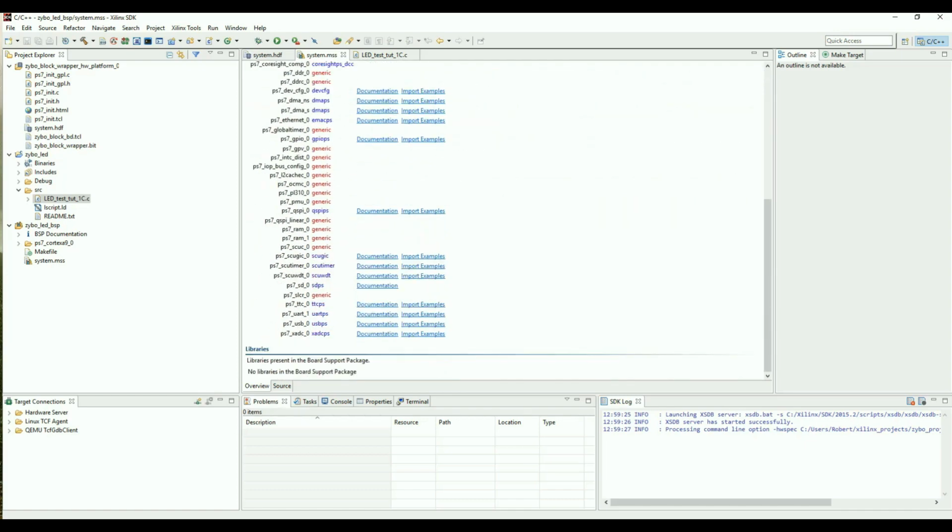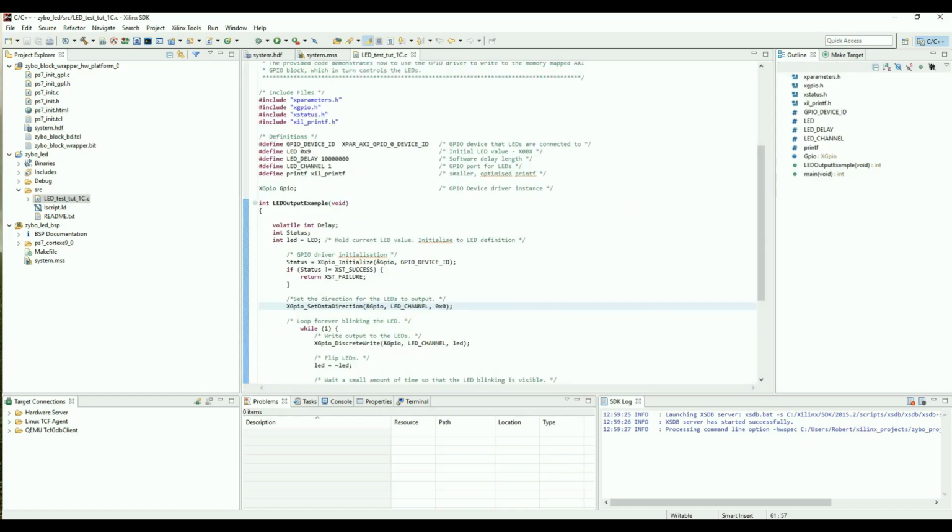Here's the AXI mapping. Again, we're memory mapping here. The address space from the Xilinx Vivado for the GPIO port corresponds to what the ARM will be addressing. So your C code can interact with your FPGA modules, and this is done through memory mapping.